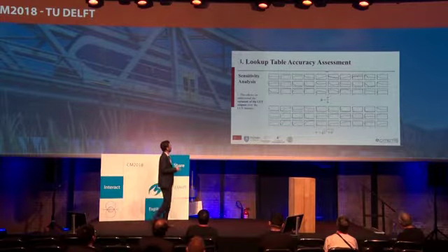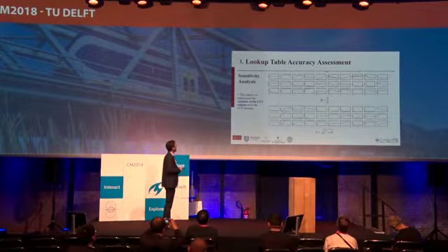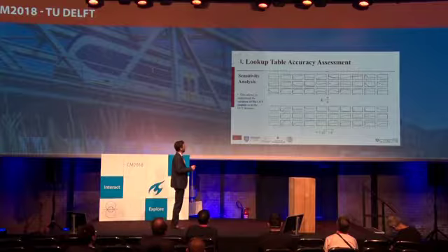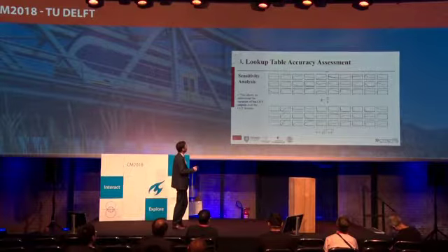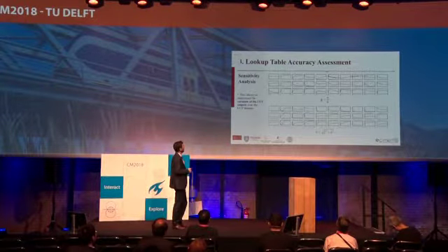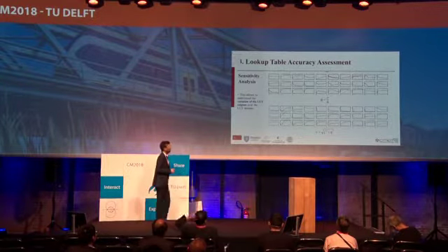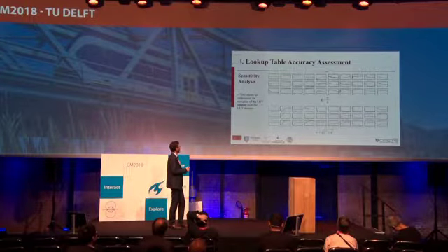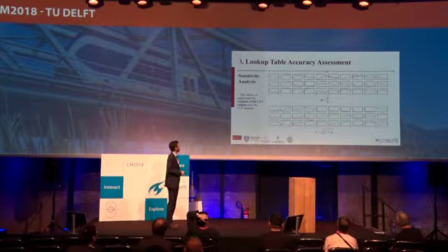It's just to show how the values for the Fx, Fy, and M forces and moments change with some of the tabulated parameters, like in this case the shape factor for the ellipse, A over B. And you see there is a quite strong nonlinear effect of this parameter, which sometimes looks like a logarithmic trend, and I will come back to this later on. Also, the magnitude of the non-dimensional creepage is very much affecting, especially in the low values, whereas in the high values we see a much smaller effect.